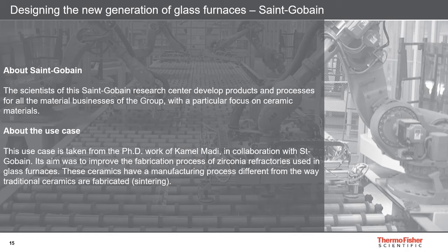This example is taken from the PhD work of Kamel Mahdi in collaboration with Saint-Gobain. Its aim was to improve the fabrication process of zirconia refractories used in glass furnaces. The ceramics have a manufacturing process different from the way traditional ceramics are fabricated, sintering. They are formed by solidification, similar to the way metals are formed during foundry: electrofusing, casting, coating, with a microstructure